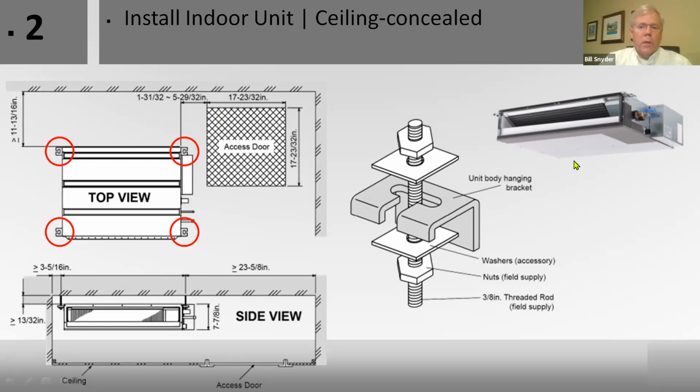And these units come upside down in the box. These little fingers here to hang it on that they're showing here in red circles, these actually point down when you're hanging this. I've gotten phone calls and done this myself where you lift it out of the box, lift it straight up and hang it, and find out later that it's upside down. So you just be very careful of that.